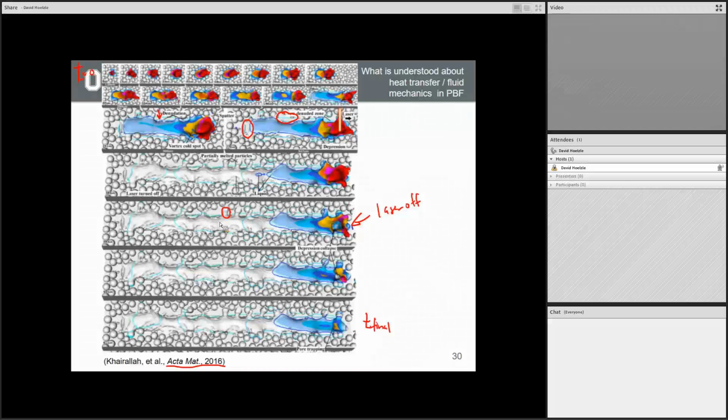Depends what you need. The part I passed around, you can actually feel it's rough, right? It's not like what you get off a CNC mill, which oftentimes has a very smooth finish. So it depends from an engineering point of view what you need. If you need a very smooth surface, then you probably have to do some sort of finish machining on it. If it's not a requirement, then that's probably an unnecessary expense to go through and make it smooth.